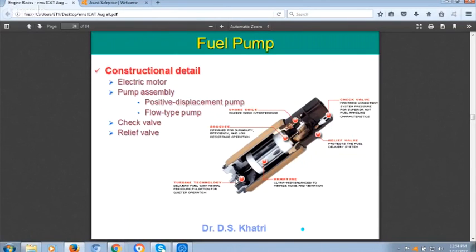Another point, there is a winding, that copper wire. If there is an acidic nature of the fuel, it eats the copper. It will not allow the current to pass through. So again, we have done a modification in the pump. When the Swift diesel was launched, the pump was from Germany. So we asked them, okay, because we expect that it should meet around 20,000 hours of reliability. They say, okay, we have done it in Germany and it is there.